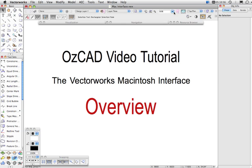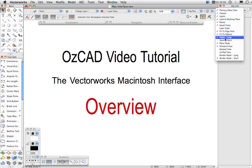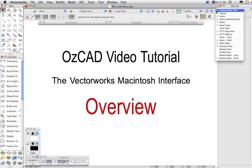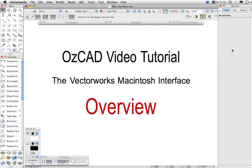If you don't need to see the zoom percentage, then you'll also see there's a zoom long and a zoom short. So if we set to zoom short, then we won't get the actual percentage. One thing that you may want to put in here is rotated view, and this allows you to rotate the drawing for drafting purposes.